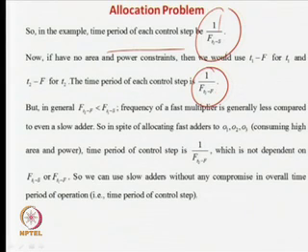Now, if I take a very slow multiplier, you will be in another big problem, because the time period of the slow multiplier may be, say, 50 nanoseconds, and then each of the time steps will be 50 nanoseconds. So, I will not take a slow multiplier; I will take the fastest multiplier and a slow adder, because the multiplier is determining all the time steps, being the slowest element in the whole schedule of operations. If another block is doing a very complex operation, such as a factorial computation,